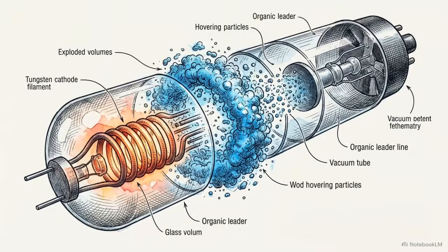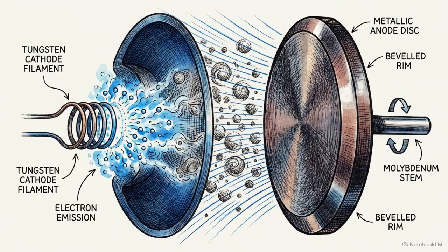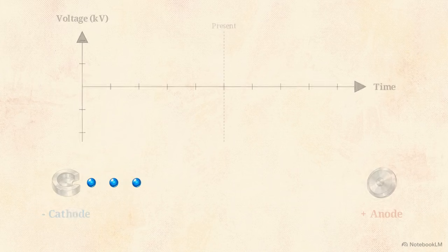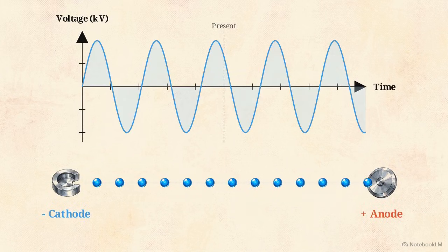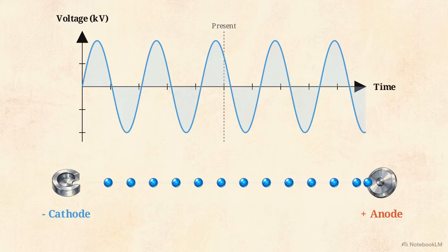But a static cloud of electrons is useless on its own. They need to strike the positively charged anode target across the gap. To pull them across, the machine applies an accelerating potential, or tube voltage, measured in kilovolts. This creates a steep negative to positive gradient.